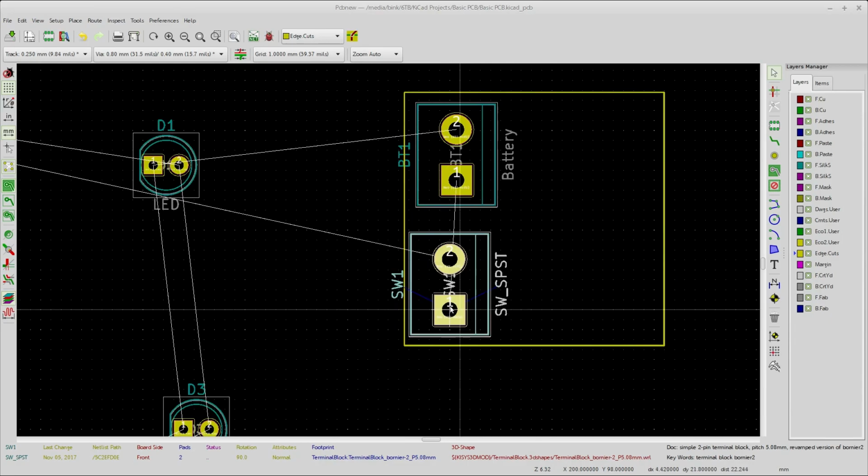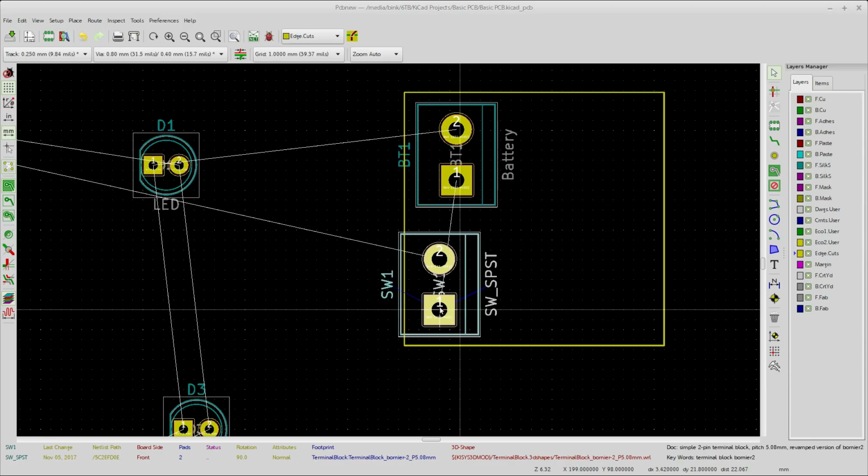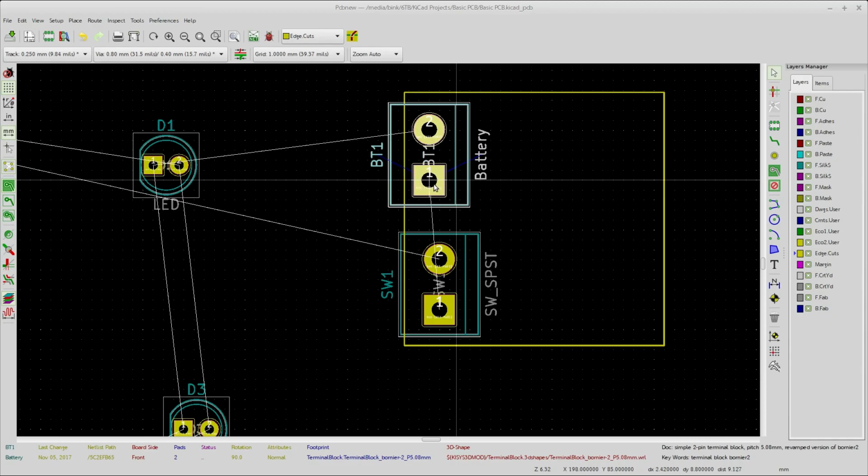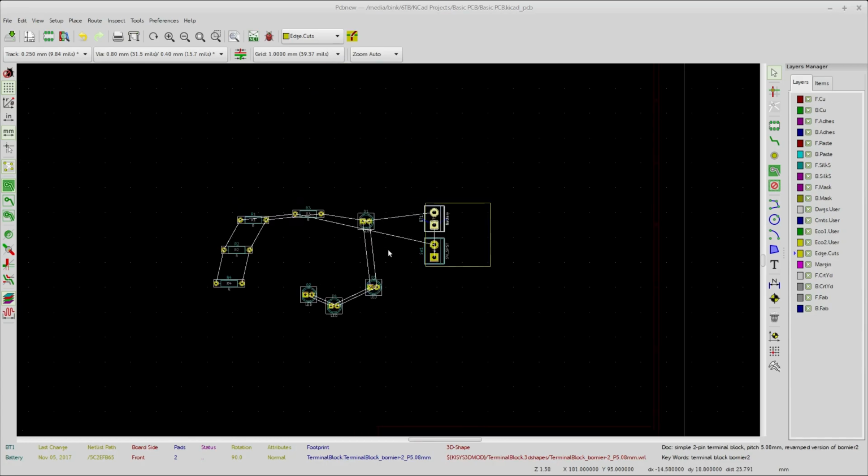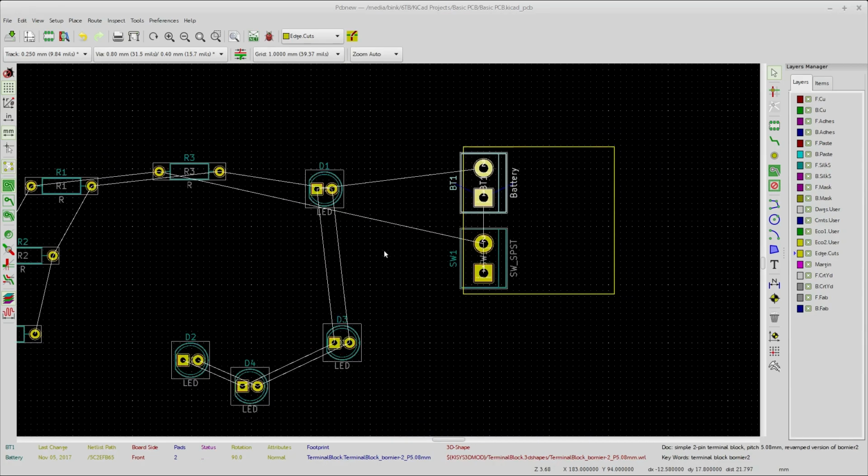Also realize this footprint that we chose has got an outline on it, but we don't necessarily need that. I could scoot this all the way up to here, you know, if you like. That's not a bad idea. Pick this one, move that up. There, now they're kind of even. Then we need to move the resistors in, I guess.